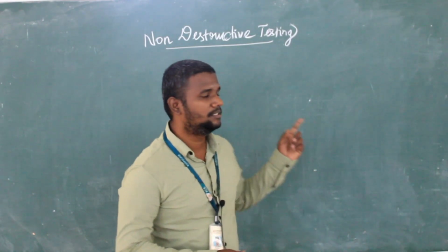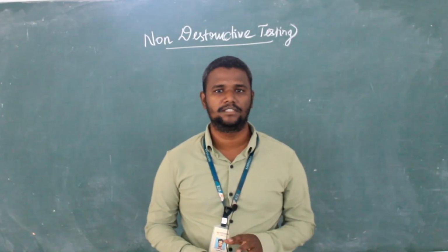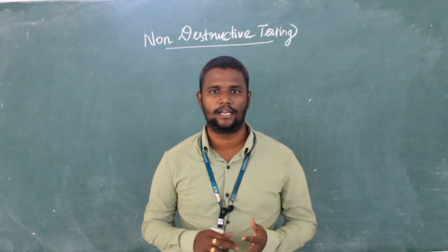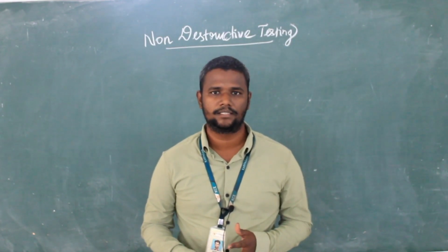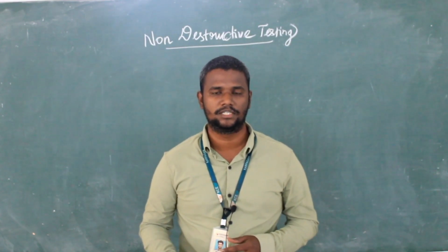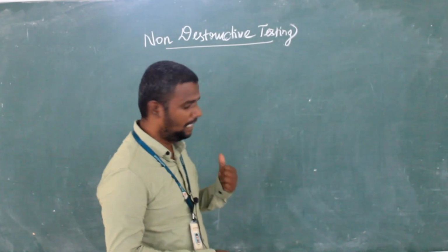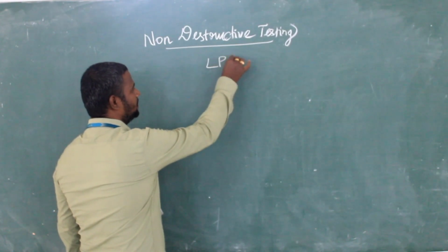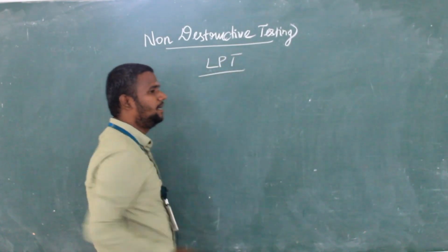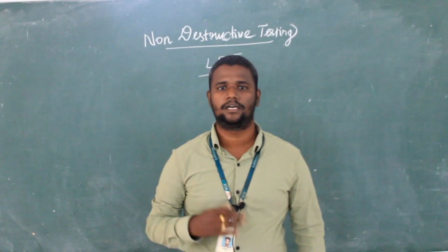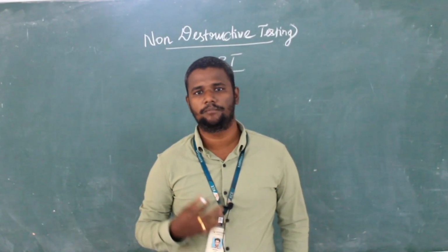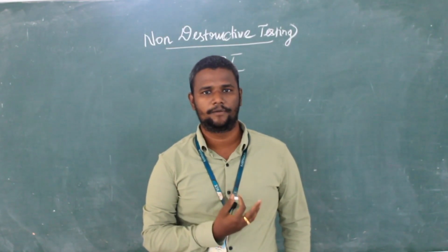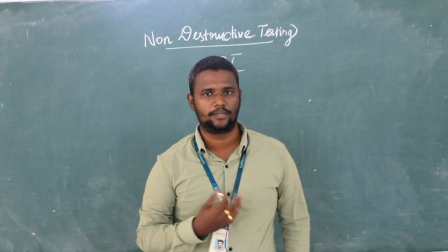In non-destructive testing, we have different kinds of testing, like liquid penetrant testing, magnetic particle testing, radiographic testing, and ultrasonic testing. Here I have selected liquid penetrant testing, in short form LPT. LPT is used when the other tests cannot explain the defects. So that is the advantage of liquid penetrant testing.